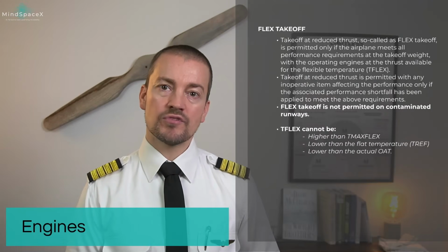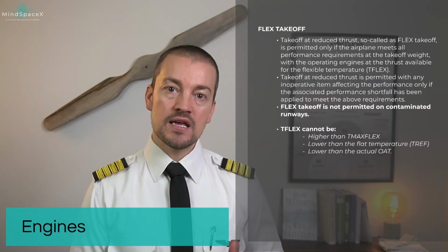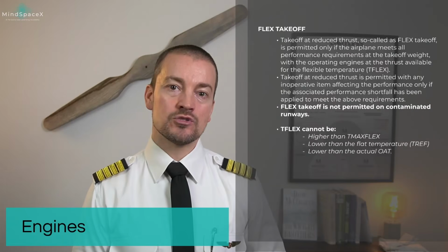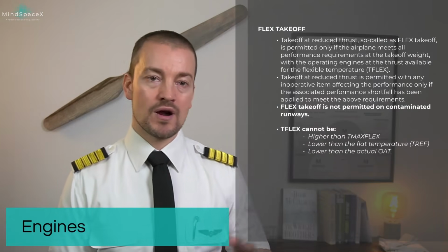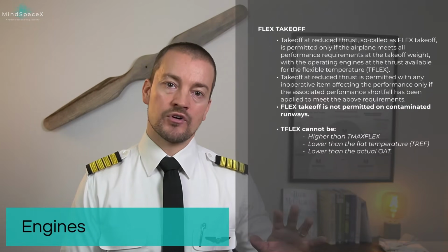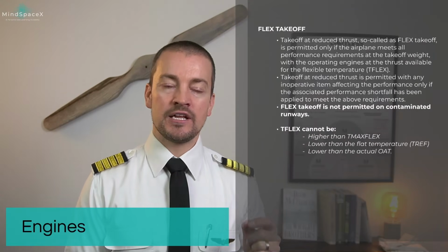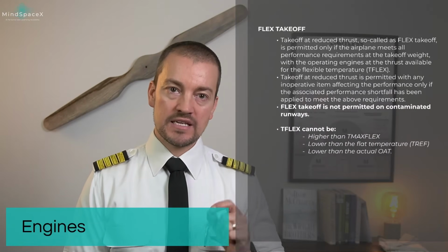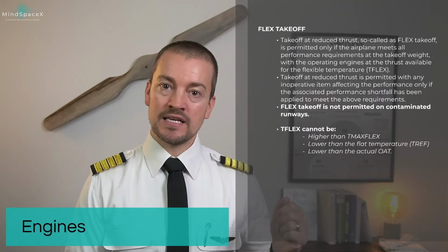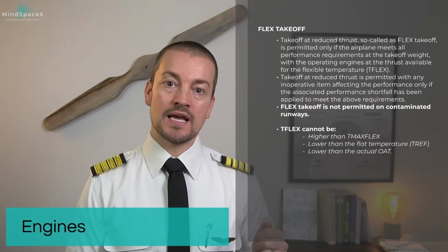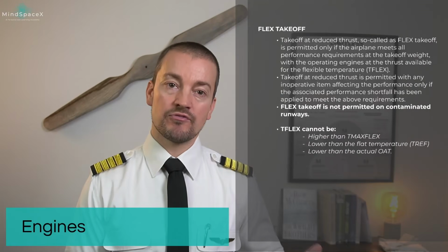Takeoff at a reduced thrust is permitted with any inoperative item affecting performance only if the associated performance shortfall has been applied to meet the above requirements. It means you have used the appropriate tables to account for said failures. All of this is covered in the performance course. Flex takeoff is never permitted on contaminated runways. T-flex, that means the temperature value for flex, cannot be higher than the T-flex max, lower than the outside air temperature, or lower than the flat rated temperature, T-ref, for the engine.